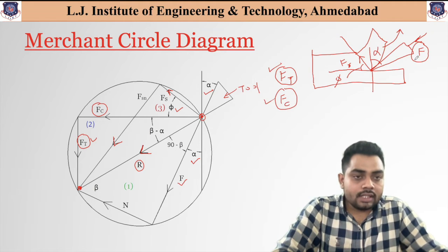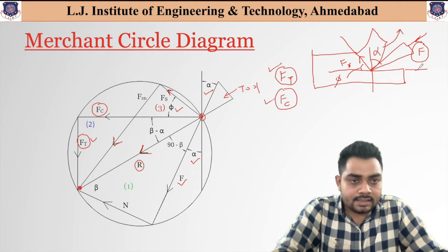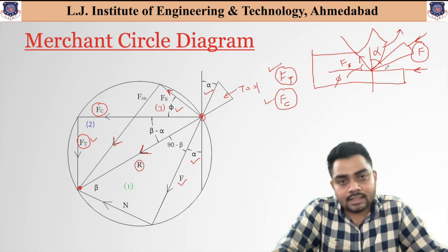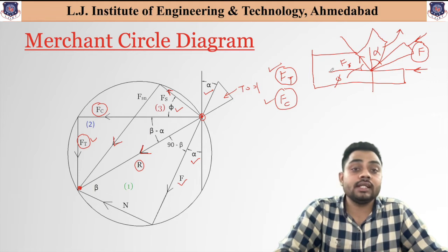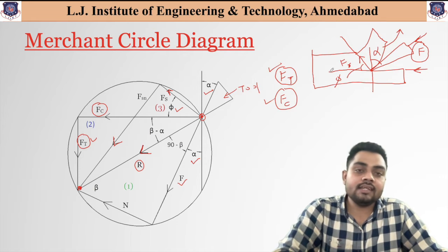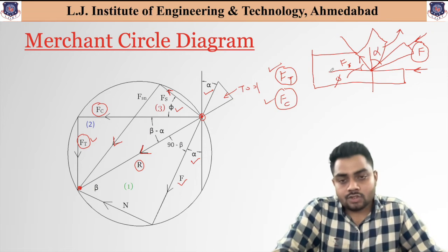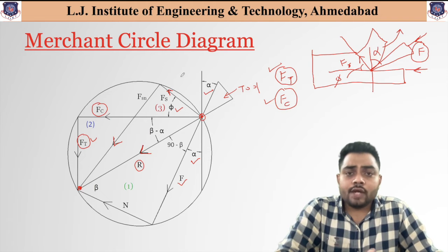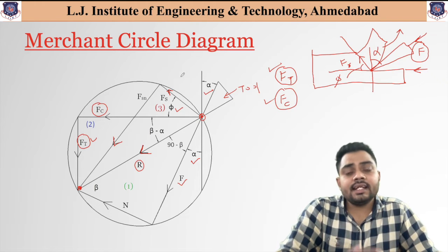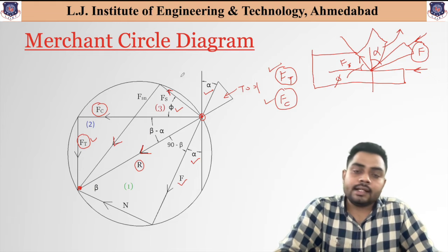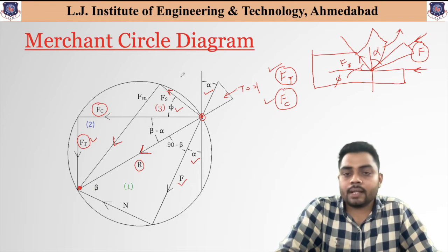Why? Because we know that the cutting is taking place in this direction. As we are moving forward in this particular direction, then and only then is cutting happening, and that's why we indicate it as the cutting force Fc. So now I hope you have clarity about the forces that are indicated in this particular diagram. So the indication of your diagram is complete.